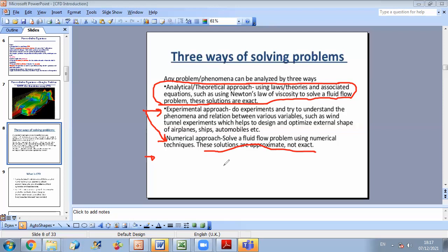So we can do a small experiment to validate the CFD model. This will allow us to tune the parameters. So in case, for example, the mesh should be enhanced in order to have better results. If we have a transient application, we might have to decrease the time step to reach a more exact solution, etc. So experiments can allow us to tune our model, and once our model is working well, we can use it to perform a parametric study.